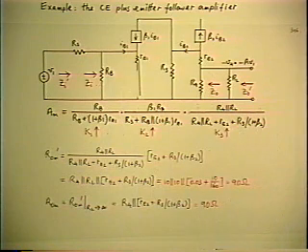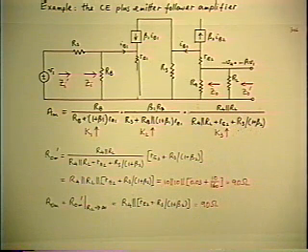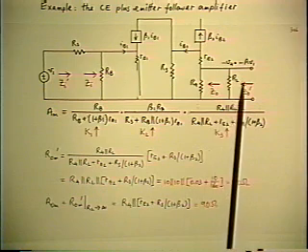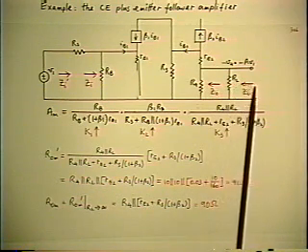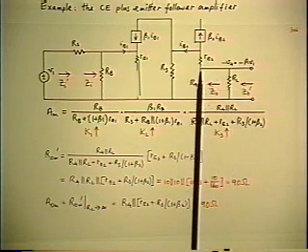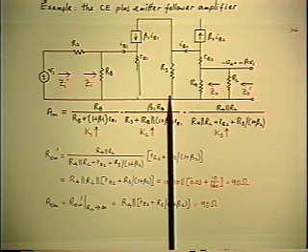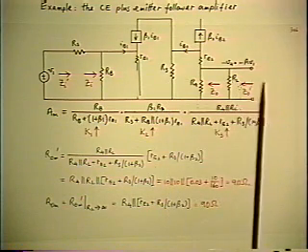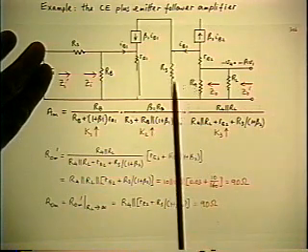Well, as usual, when we're practicing a new technique, we do it first on a very simple example, such as this one, in which the answer is obvious anyway. Because it's easy to see by looking in at the output that the outside output impedance is R4 parallel RL parallel RE2 plus the reflected R3. Because if you were to derive the output under conditions of 0 V1, that's the answer you would get.